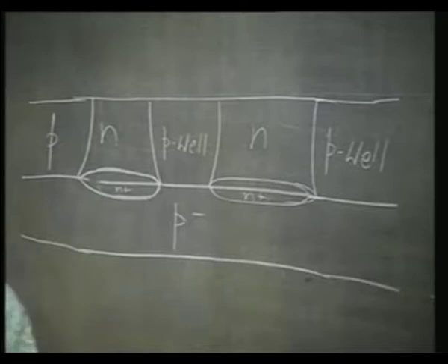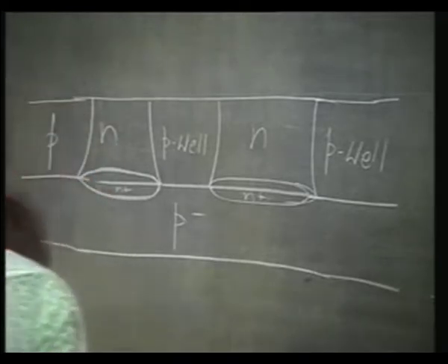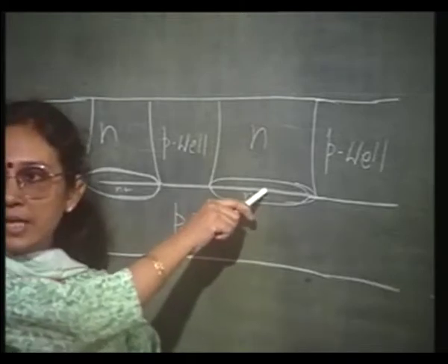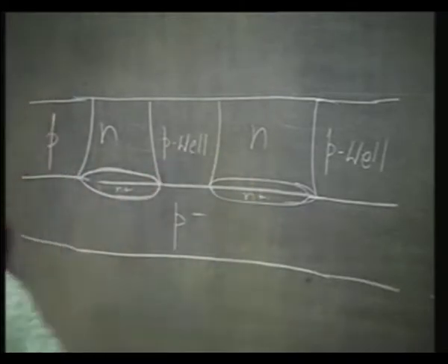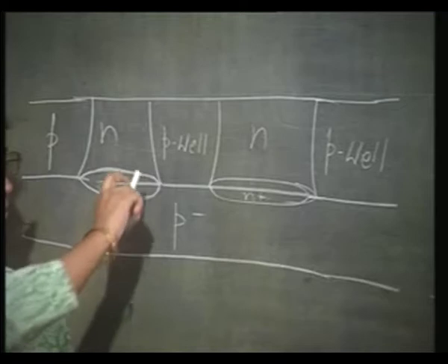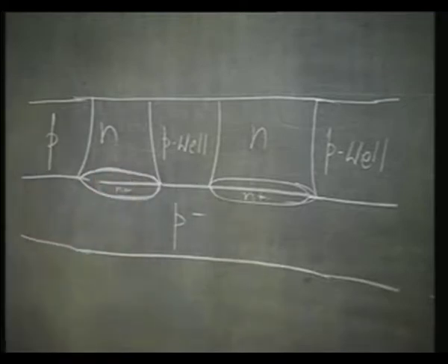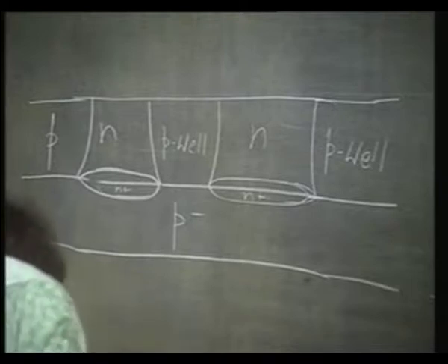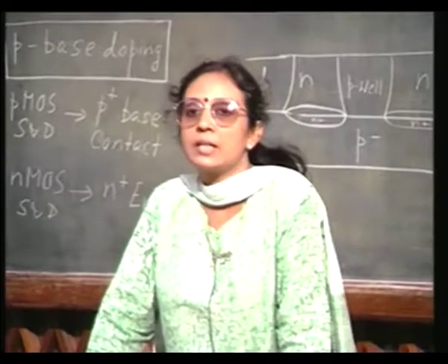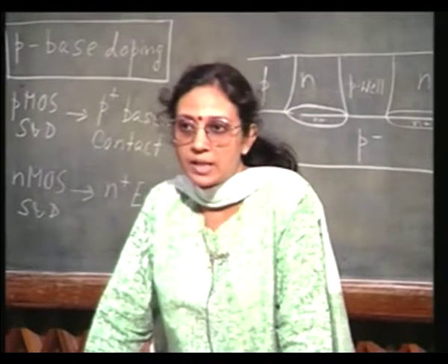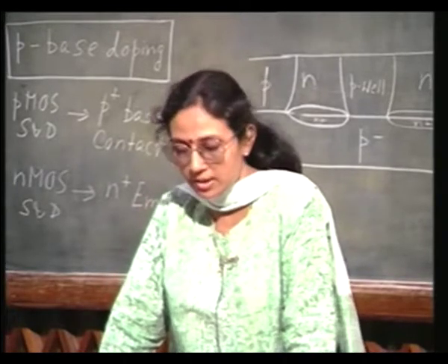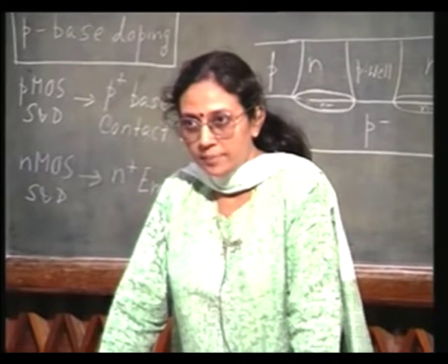So, even though I have actually added two steps, one of the buried layer and the other of the epitaxy, this is in fact, if you remember, your retrograde well with epitaxy, which can be used both to prevent the latch up in CMOS as well as to cut down the collector resistance in bipolar junction transistor.